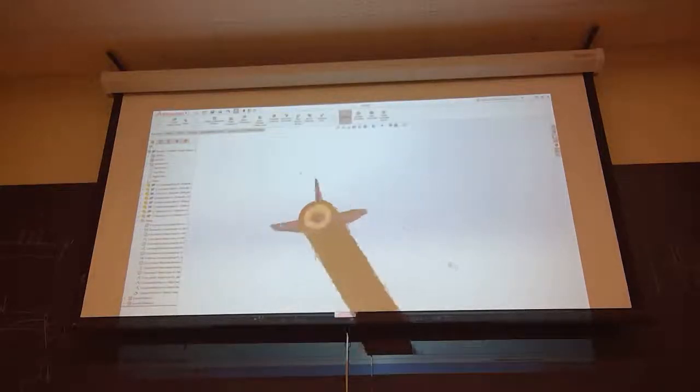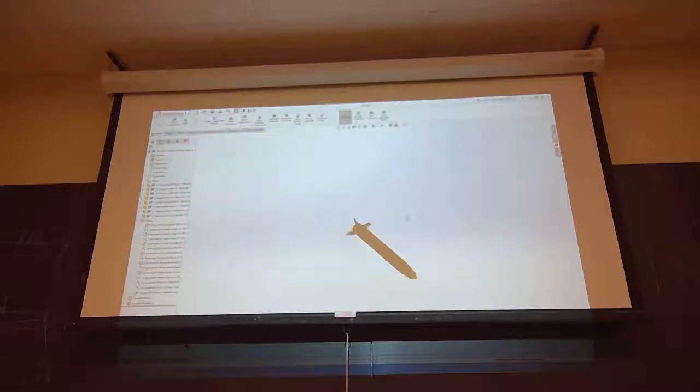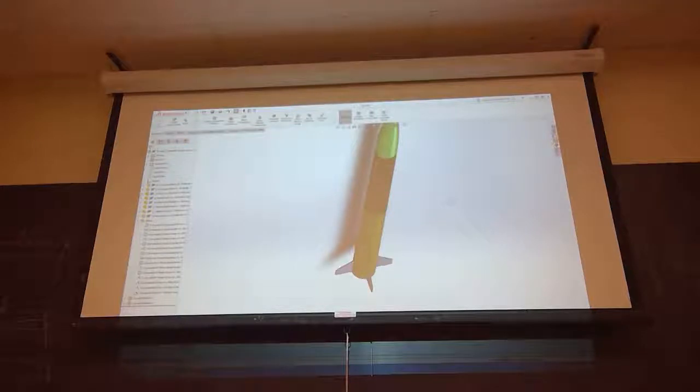Yeah, it's just a circular pattern instead of a linear pattern. Make sure you hit equal spacing. You don't actually have to touch that. You can just hit equal spacing. And then parameters. What are we rotating? So you want to select something that we're rotating. And equal spacing.